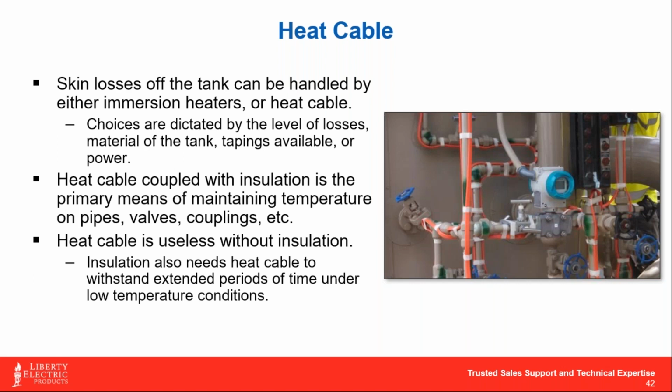And again, what we typically will do is a heat loss calculation to find out how much we have to offset, and then recommend the right wattage cable for that task. Keep in mind that heat cables generally cannot offer up enough heat to actually transfer heat through the pipe itself and affect anything within it.